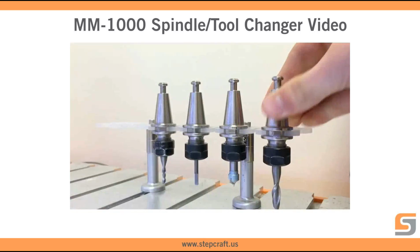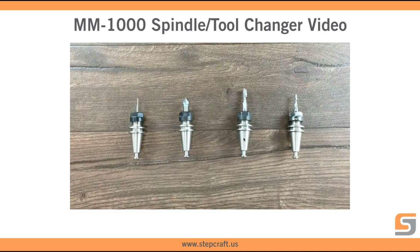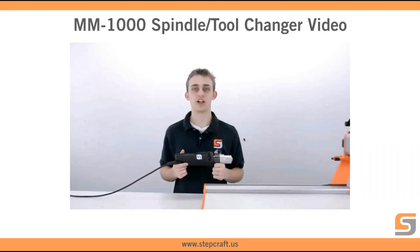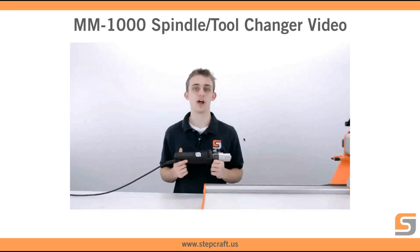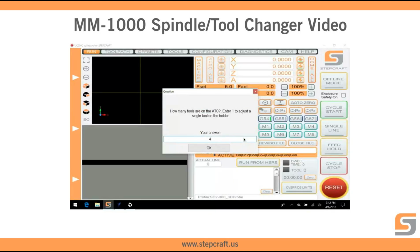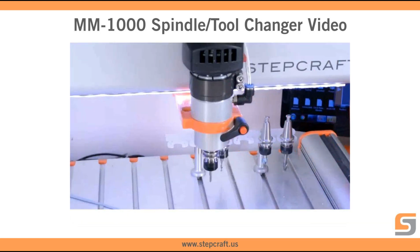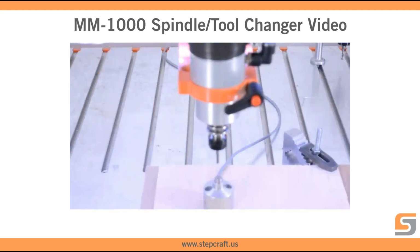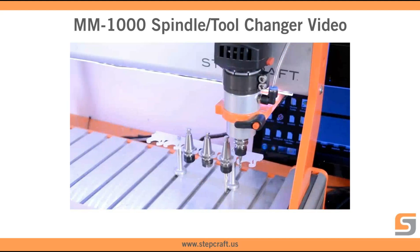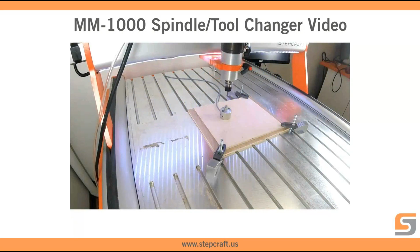The tool holders for the ATC are very robust, and they use a standard ER11 collet. This allows you to use a wide variety of tool shank sizes for an almost endless selection of end mills and cutting bits. While the functionality of the automatic tool changer works flawlessly, we wanted to ensure that setting up your tools for each job was quick and painless. To accomplish this, we developed custom macros for UCCNC that allow the ATC to work just like the ones found in very expensive industrial CNC machining centers. Simply load your tools into the tool holders and place them in their respective locations on the tool rack. The software will automatically measure the tool height offsets for each tool and store them in the system.